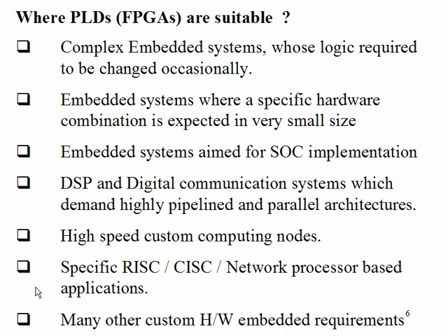You got the point? It's an in-depth point, but what I want to say is the concepts like pipelining and parallel execution units become very useful in the case of RISC in comparison with the CISC case. CISC follows different approaches to improve the speed. Today both are giving high speeds, but when you talk about an embedded application, a very specific application, we go for RISC. That's more suitable. For general purpose, we go for the CISC solution.